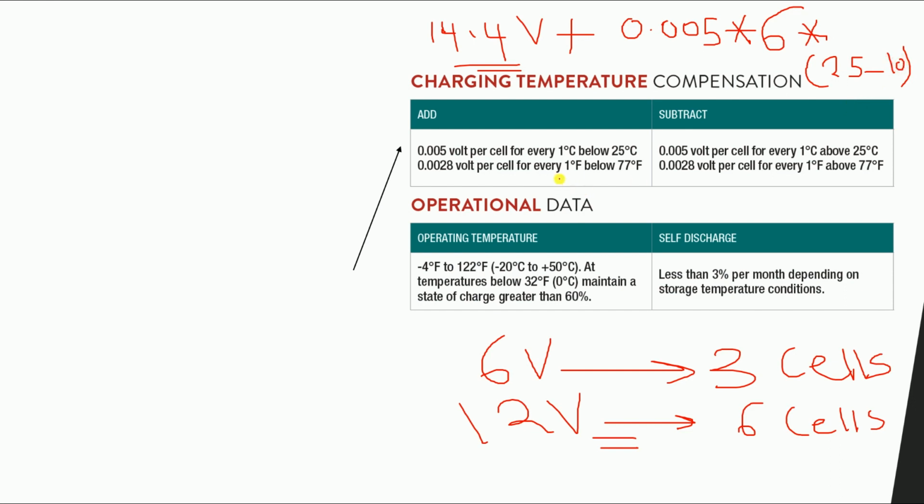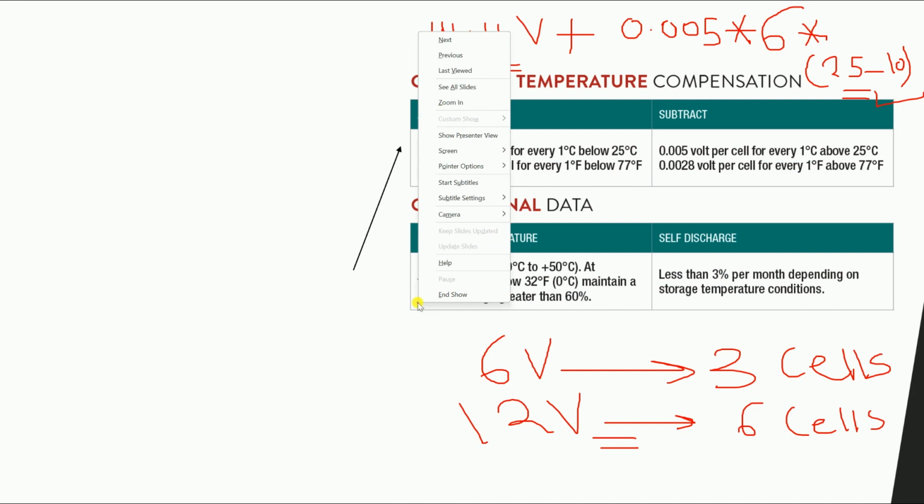Same for Fahrenheit, you will add this for every 1 Fahrenheit. This will give you the new voltage. Now, if you are going to an increase in temperature, you will make this one a negative sign. This little compensation will help us with the change in temperature, as the change in temperature leads to a change in the charging voltages, absorption, float voltage, and so on. So you need to add this small change as a compensation for the charge controller itself.